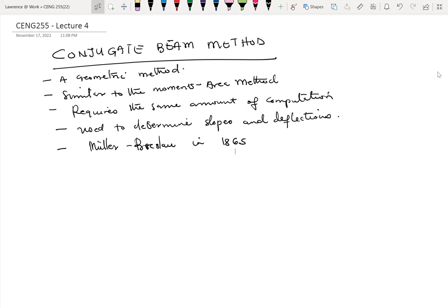I also mentioned a few weeks ago that when you have to design a structure, even when using a software program, maybe Prota, STAAD, ETABS, SAP or whichever engineering product you have at your disposal, you still need to do some hand calculations to see if they agree with the output the computer has, so that you are at least confident of the outputs from your computer.